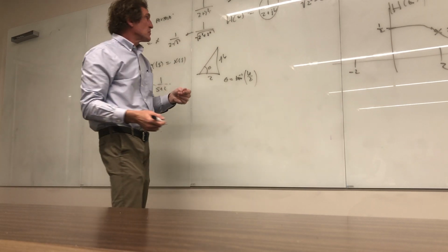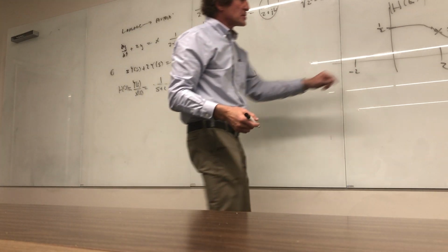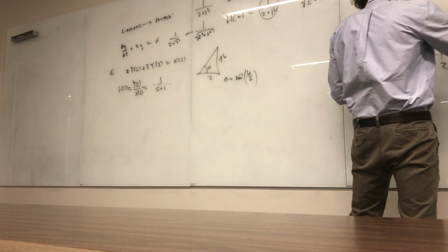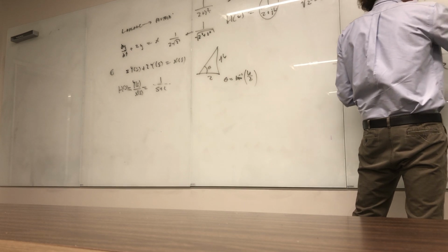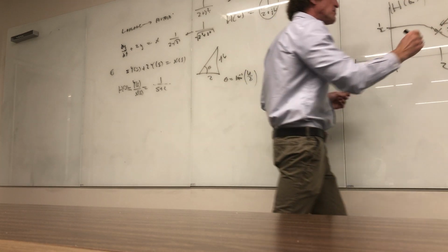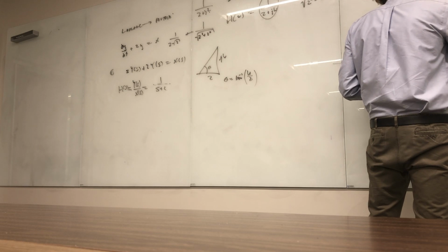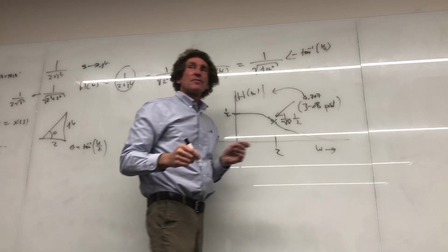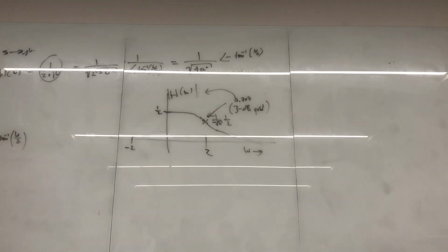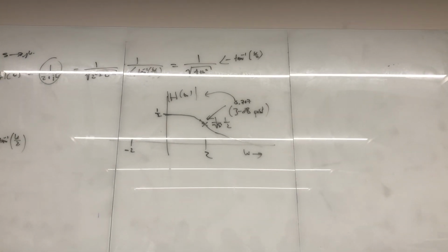It's over 1. So it's what? It's reduced by 1 over the square root of 2. This is actually 0.707, the peak value. It's called the 3 dB point. And write that down. It's the 3 dB point. And it's the point where the voltage drops by, or current drops by 1 over the square root of 2, and the power is 1/2. It's called a half power point, usually.